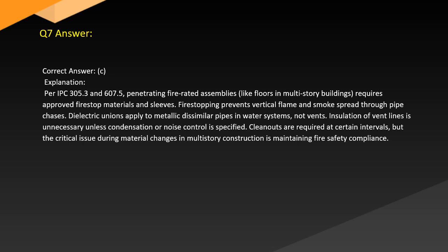Dielectric unions apply to metallic dissimilar pipes in water systems, not vents. Insulation of vent lines is unnecessary unless condensation or noise control is specified. Cleanouts are required at certain intervals, but the critical issue during material changes in multi-story construction is maintaining fire safety compliance.